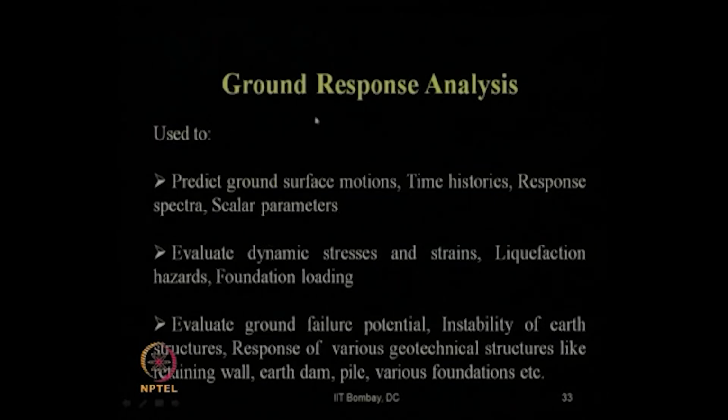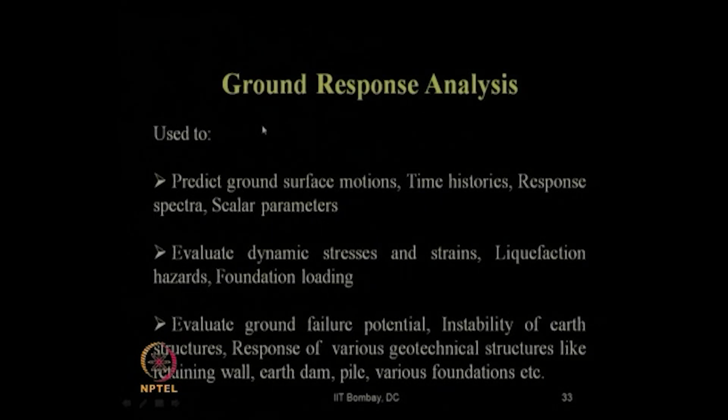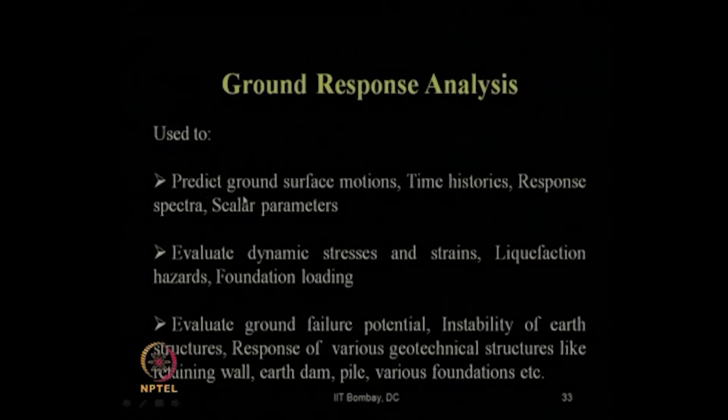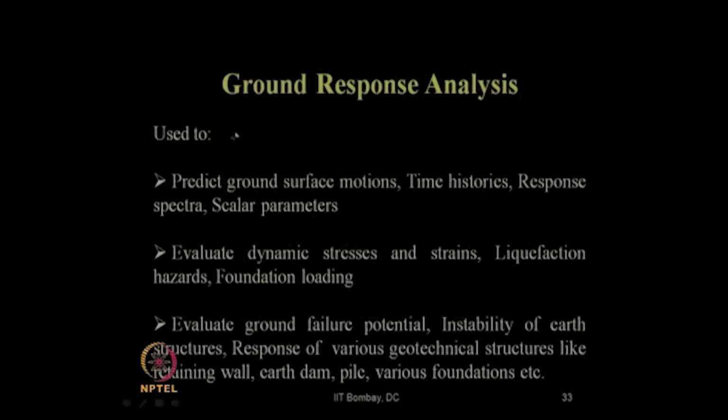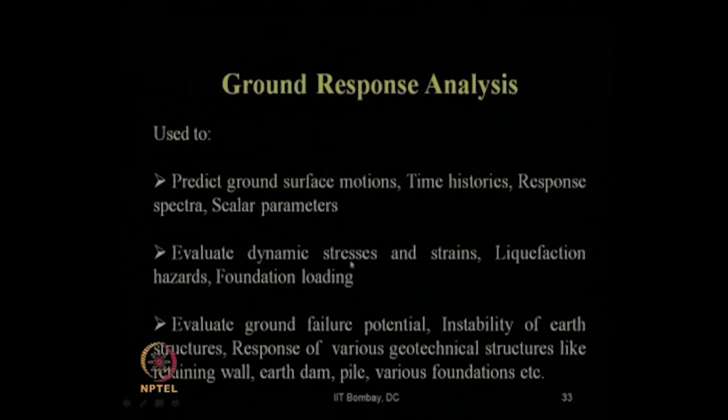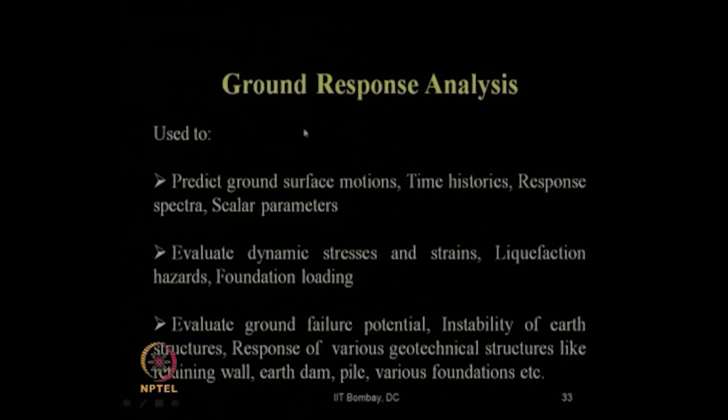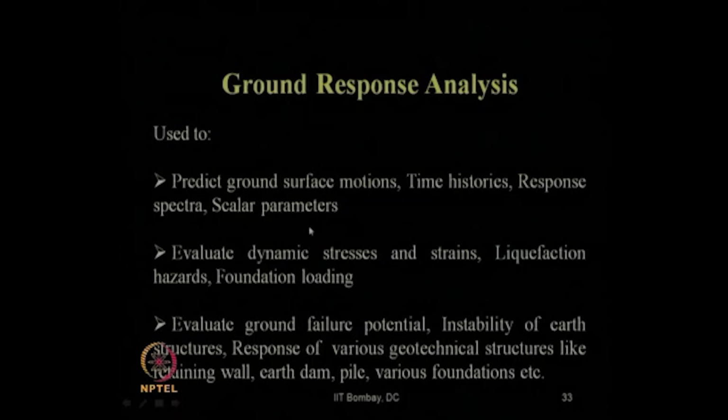So, for that, what do we need to do? Ground response analysis is used for predicting ground motion parameters, time histories, response spectra, scalar parameters, etc. Ground response analysis is also used to evaluate the dynamic stresses and strains in the soil, liquefaction hazard, and foundation loading, that is, what extra loading is coming on, say, a pile constructed in soil.